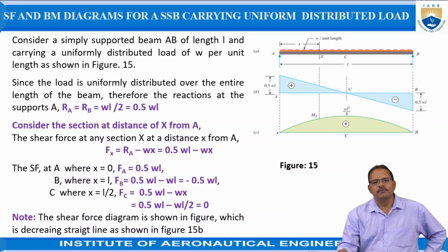And since the body is in equilibrium, by using that fundamental, it is required to determine the reactions at A and B, that is at the supports as shown in figure, for drawing shear force and bending moment diagrams. Here in this problem, consider a simply supported beam of length L carrying uniformly distributed load of W per unit length, as shown in figure 15.